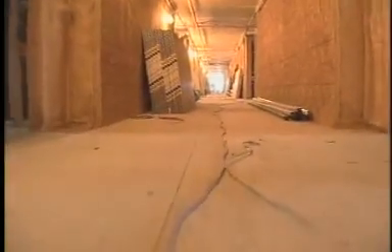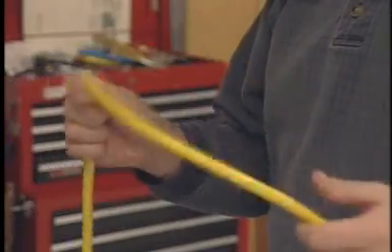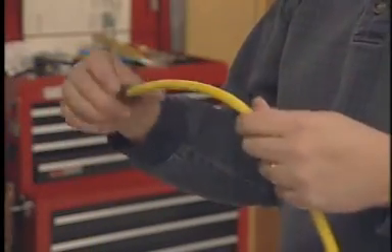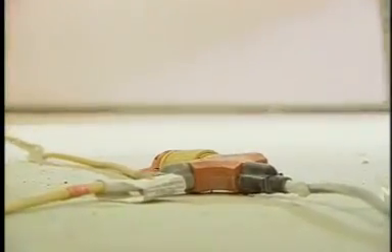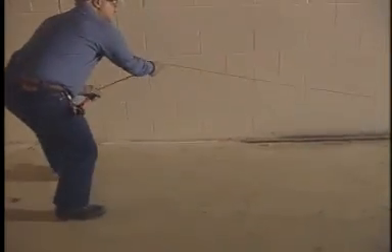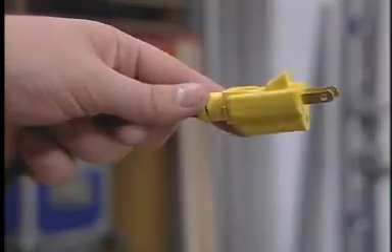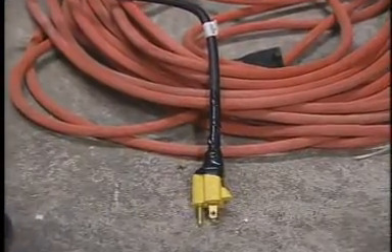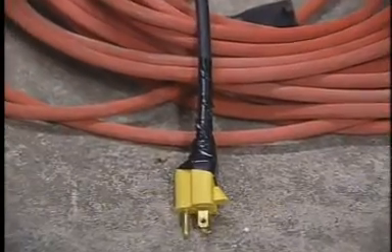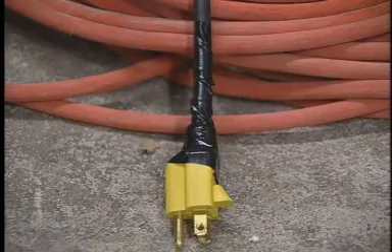When you use extension cords, keep in mind that they really are designed for temporary use only. Only cords that are designed for hard or extra hard service should be used at construction job sites. You'll see these designations marked right on the cord itself. Keep extension cords out of the way of others. Don't use worn or frayed extension cords. As well, don't use cords with missing third prongs or that have been so-called repaired with electrical tape. Electrical tape doesn't really repair a cord. It only covers up a potentially dangerous situation.